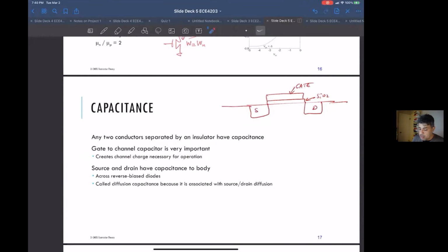You're going to see it in your project too. And this is the capacitance of, these look like diodes, right? This is N plus into a P. So it looks like a diode. This looks like a diode to this device. And this capacitance, if you can minimize this capacitance as much as possible, that's what you'd like to do, right?